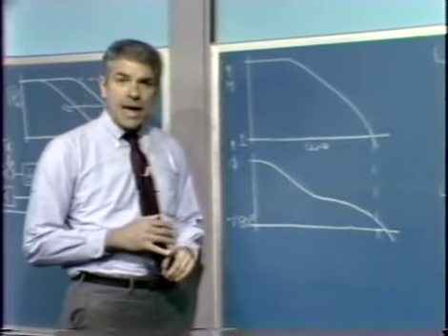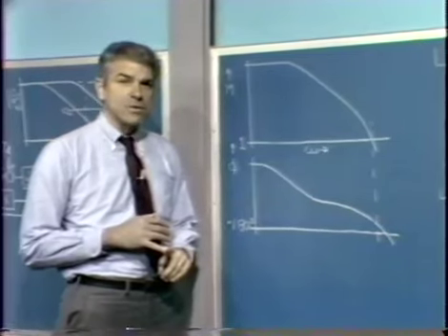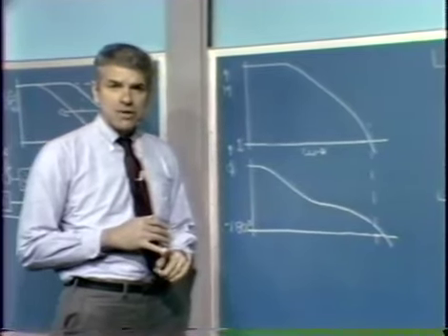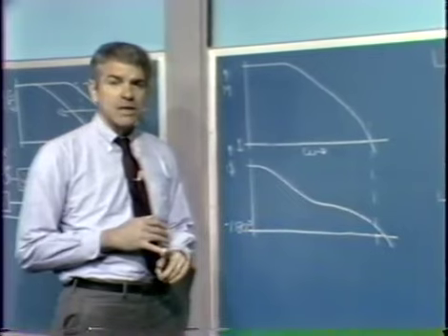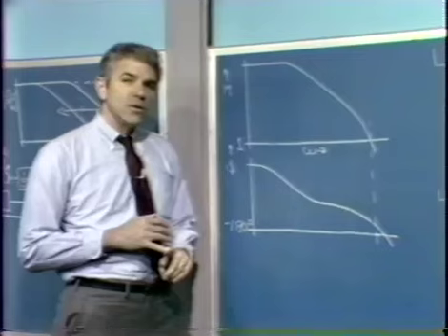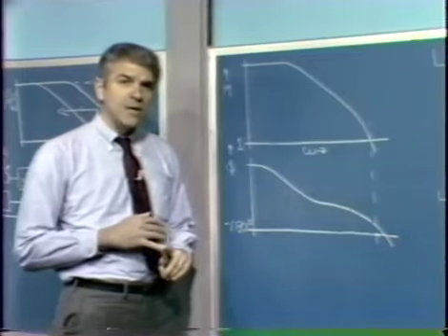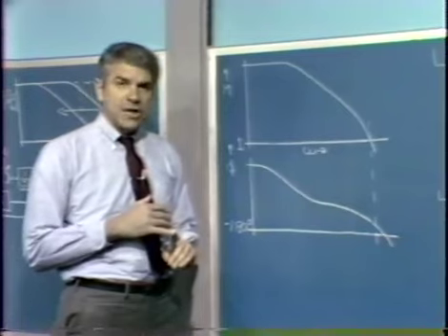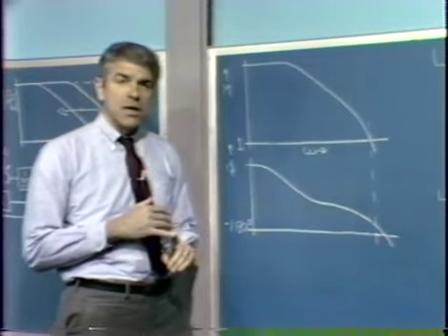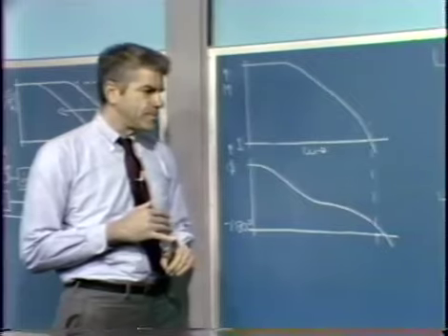Either push up the angle portion of the Bode plot in the vicinity of the crossover frequency without making a corresponding change in the crossover frequency or the magnitude, or push down the magnitude curve in the vicinity of crossover to lower crossover, without making significant changes at much lower frequencies, and without modifying the angle associated with the transfer function.